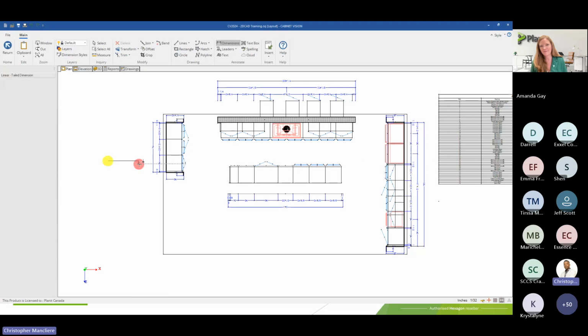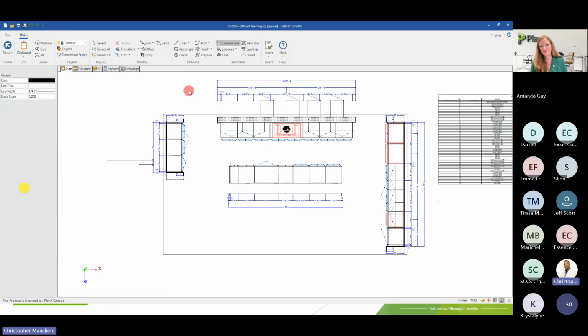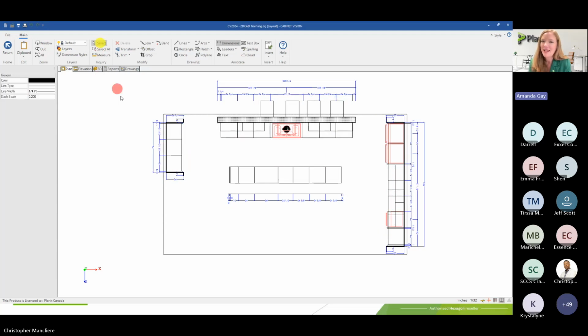Then you can add any dimension that you want. And what will happen is, even if you exit your CAD tool and go back and go to dimension again, it will still save it as a tail by default now. So tail becomes your new default for your dimension. Got it. Thank you.